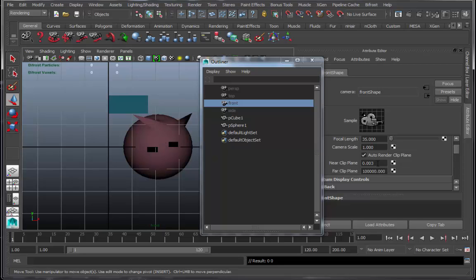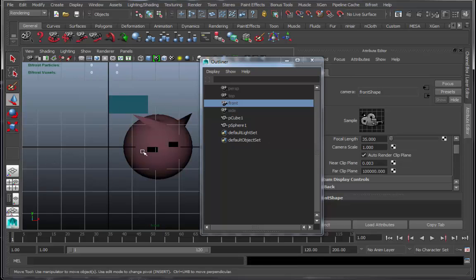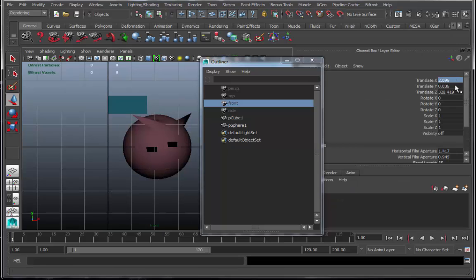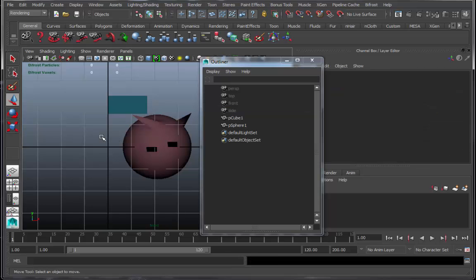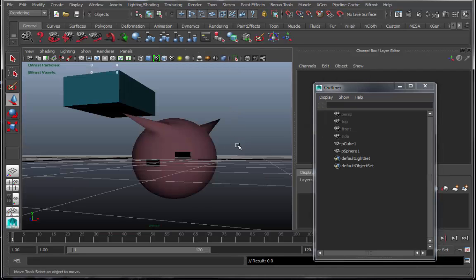And if the near clipping plane is not working, you may have to actually grab the camera and make sure that the camera is pulled back far enough away from this object that it can see what it needs to, and it's not too near the camera, or the camera's not interpenetrating the object with proximity. So I've dragged it back to about 10,000 units here. So now we're seeing the object. We're a little more cognizant of what it looks like.